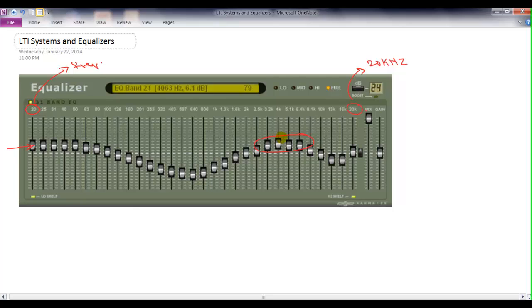They are typically designed to have linear phase, which we will study later. And what is this equalizer doing with respect to frequencies from 253 hertz to 1.3 kilohertz? It's damping them down. Okay, so effectively, if you were to plot just the positive component of that, this LTI system has a response like this.